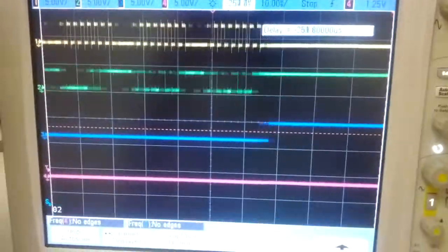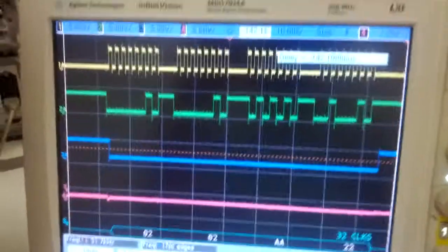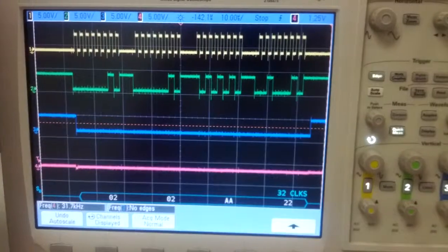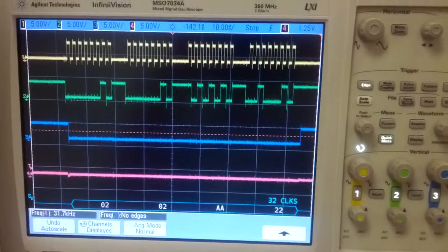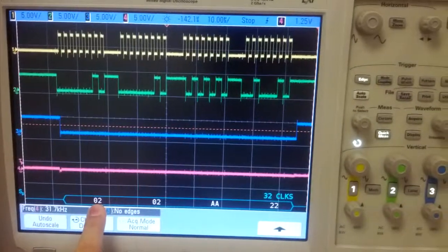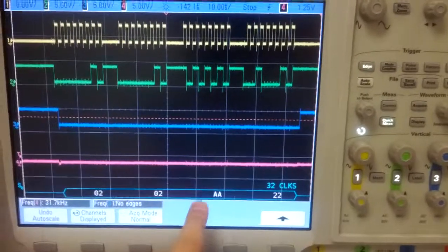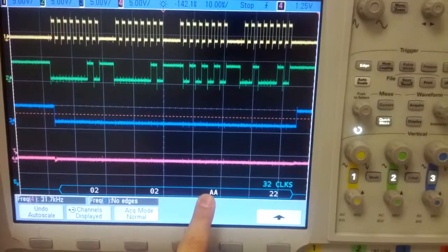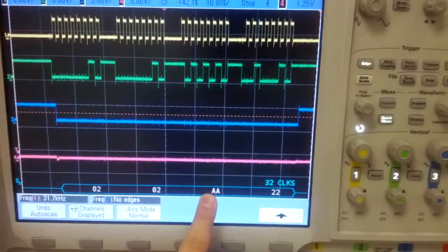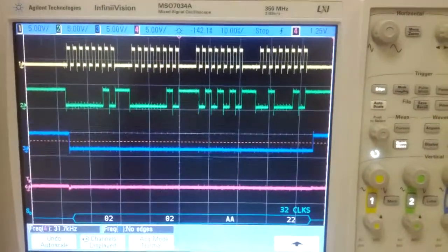And now if I scroll over, this chip has the functions of bass and treble control, and also to set my high frequency limit and low frequency limit. So this is another example of writing to the chip, where 2, so I'm writing, and 2 is the register that has these bass controls. And then these are split up into 4 separate bits where I am setting the controls as mentioned. So I'm sending in AA22.